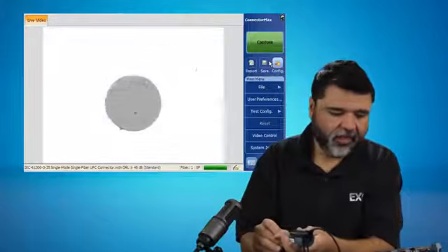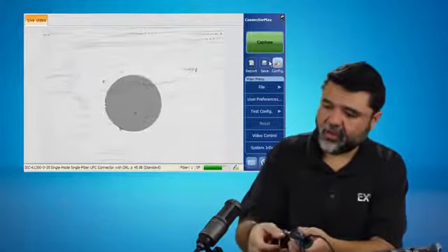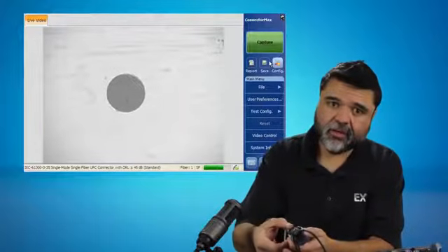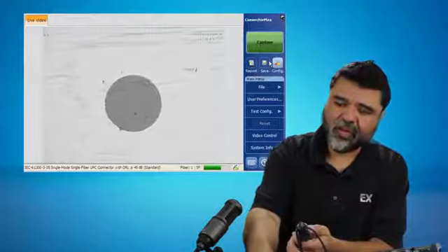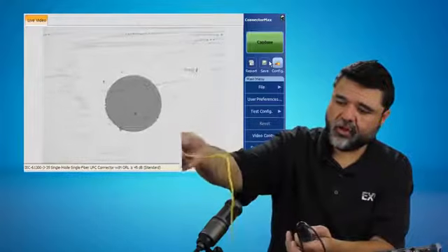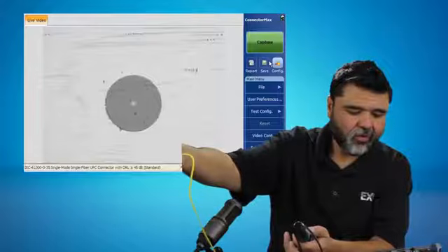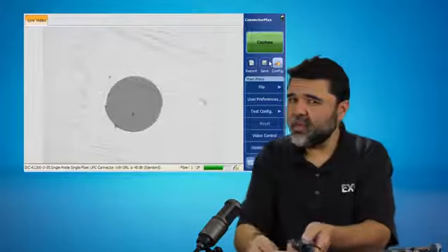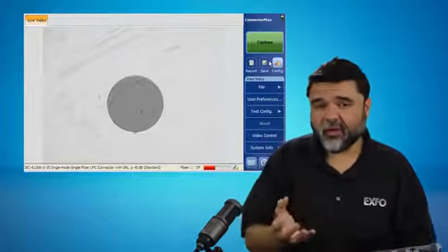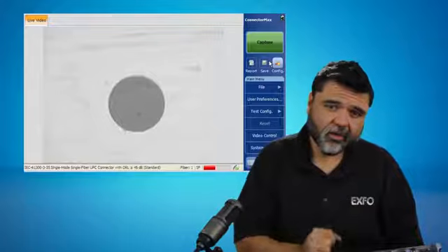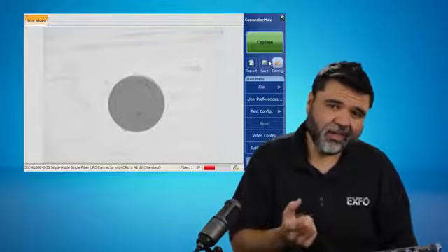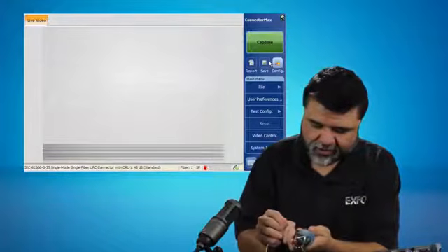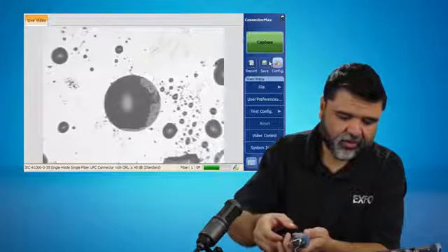I'm going to go ahead and plug in a connector that I have here, and you can see what it looks like on the end face. That's 200X there, and then that's 400X there. That dark portion is actually the cladding. You don't see the core, but if I get the light just right, there it is. You can see the core. The core is that 9 micron in the center there. Human hair is about 40 to 60 microns, so human hair is about 4 to 6 times larger than the core size of single mode fiber. Just to give you an idea of how small it is. It doesn't really take much to contaminate a fiber. I always like to show this example: I rub it on my nose and then you can see what it looks like.